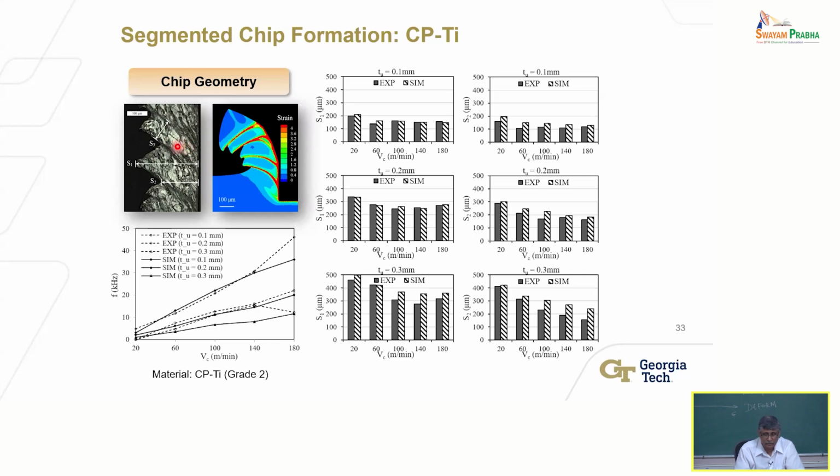And then you have what is called adiabatic shear banding. Heat cannot escape, adiabatic effect, and the material deforms a lot because it softens so much there. Very high strains are generated in that region, right? So the thermophysical properties of the material, like thermal diffusivity, are one factor in this case. But it's also a function of the cutting conditions. But thermophysical properties of the material play a pretty significant role. Okay. Also, the strain rates matter.